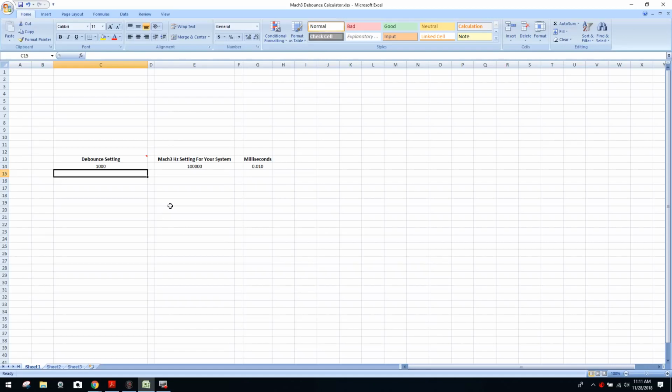I still see posted online, and again, I've discussed this with grounding. You have that old terminology where we say that ground loops are not really something to think about. It's a myth. You can ground both ends. Again, I always say ground one end. If the system is stable, go for it. If you then decide you still have issues, you can ground both ends and find out from there.